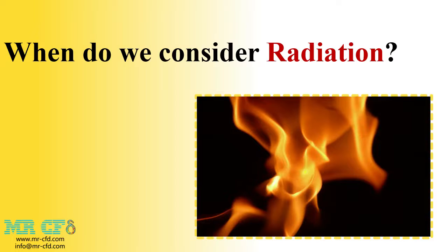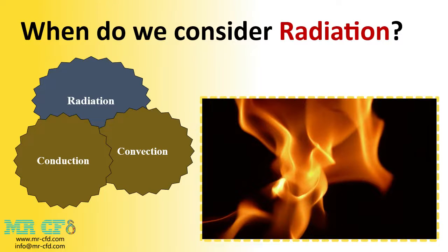This means that when the temperature is raised to the fourth power, its value becomes significant, and the higher the temperature, the more visible this fourth power of temperature is. So now we know when we are allowed to go for this method of heat transfer. When the temperature is high, it can be said that the radiation heat transfer method prevails and it can no longer be ignored compared to the conduction and convection heat transfer methods.